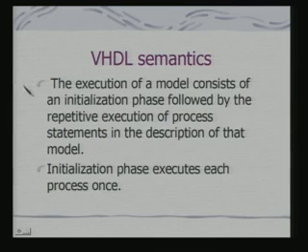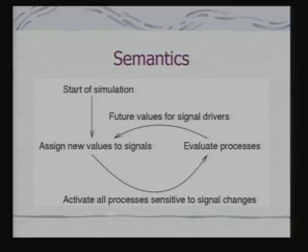What are the semantics? Once you have specified the model, the semantics tells you how it will actually be simulated. Okay? So, execution of a model consists of an initialization phase followed by the repetitive execution of process statements in the description of that model. An initialization phase executes each process once. So, basically this is the basic semantics.